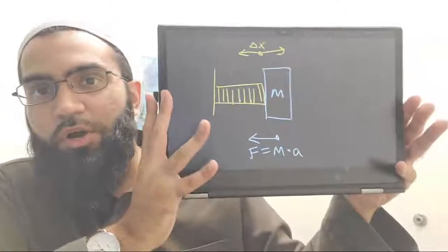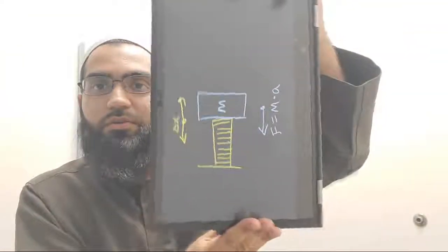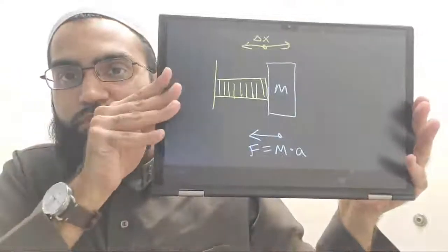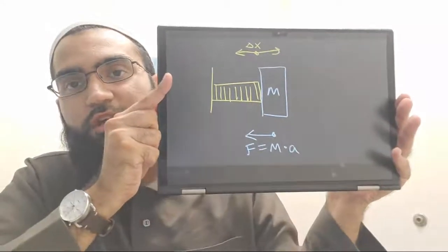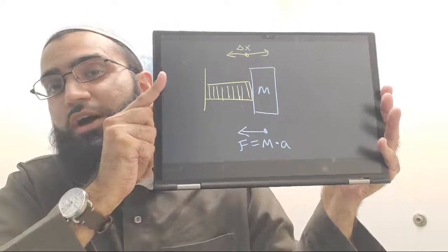All right, so we have this multilayer actuator with a mass. Let's say it's like this, or it's like this, whatever you want. So when it oscillates, the mass is going to provide an opposing force. Assume it's low enough frequency, force equals mass times acceleration. When you start to get higher frequency, you may get other types of acoustic modes where you have nodes and antinodes. In that case, the analysis is going to be much harder. I'm sticking to off-resonance actuators. You put on a mass that doesn't excite a resonance.